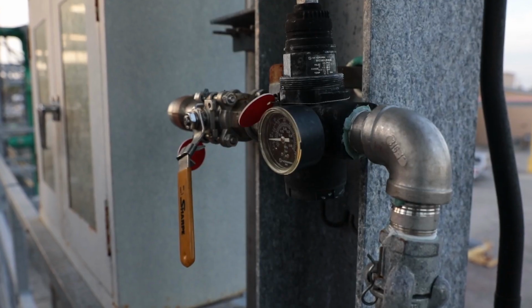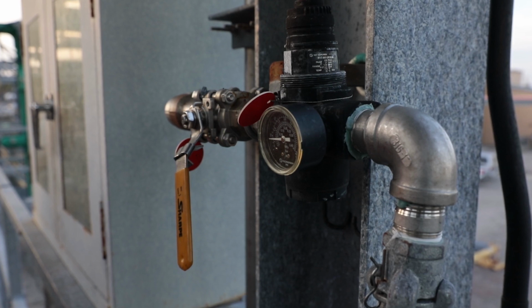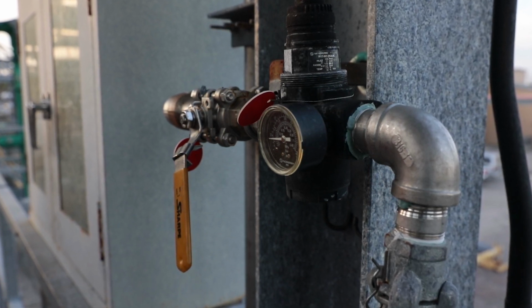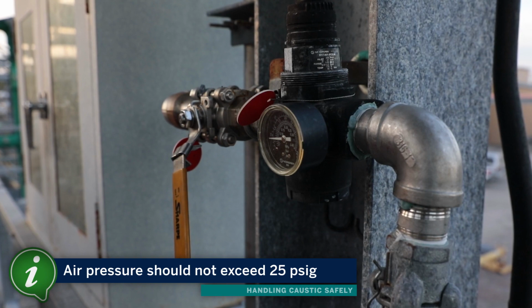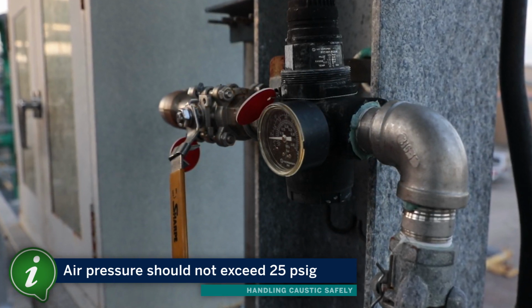The compressed air supply manifold includes a pressure regulator and pressure gauge to monitor the air pressure during the unloading and disconnecting. The regulator should be preset so that the air pressure does not exceed 25 psig.